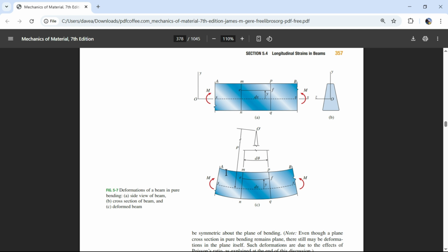Cool. So the 2 forces on the top 2 molecules crunch them in, and they stretch out in tension the bottom 2 molecules. And so this vertical line now becomes angled. That's going to be today's topic: figuring out how much these 2 get crunched in, and how much these 2 actually lengthen. If the top part of the beam gets crunched in and the bottom part lengthens, there must be a line, this dotted line, where it's neutral.